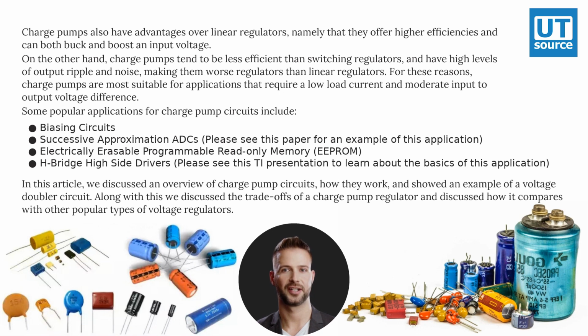For these reasons, charge pumps are most suitable for applications that require a low load current and moderate input to output voltage difference. Some popular applications for charge pump circuits include biasing circuits, successive approximation ADCs. Please see this paper for an example of this application. Electrically erasable programmable read-only memory. H-bridge high-side drivers. Please see this TI presentation to learn about the basics of this application.